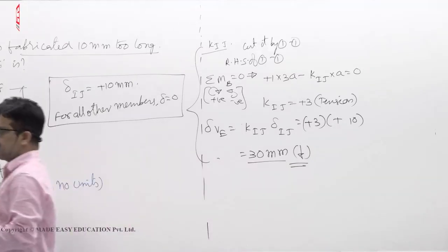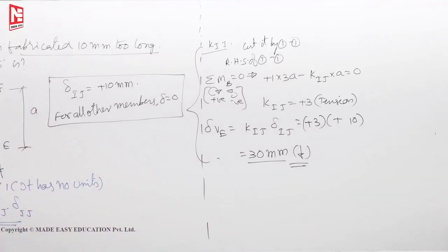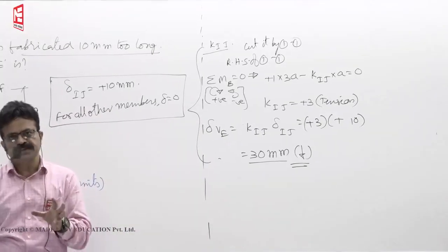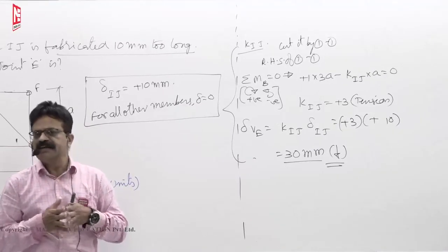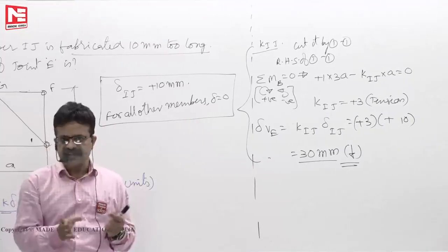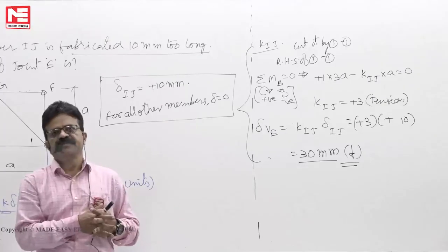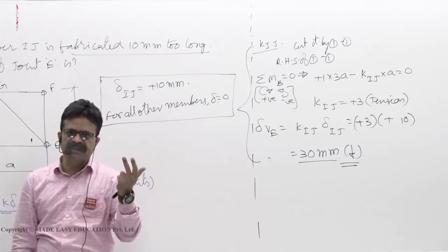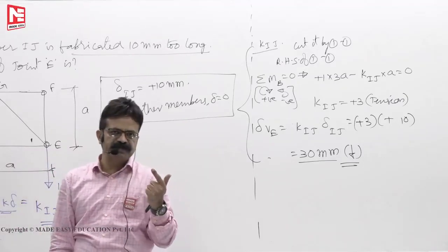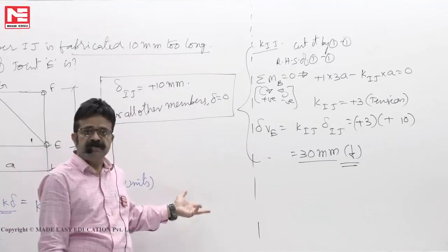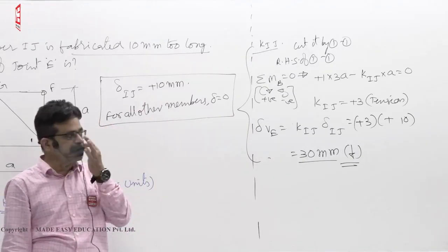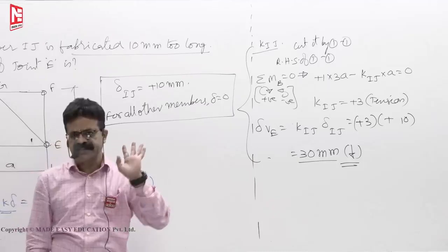Okay. So first we should have a very clear picture on the topic of displacements. Castigliano's theorem 2 is used for truss displacements. In the exam, if they give you any truss displacement, it must be Castigliano's theorem 2 only that we have to use. Either displacement, relative displacement, or rotation of any member could be due to applied loads, temperature change, or lack of fit. Okay, these are the possible examples which will be over in 2 minutes time.